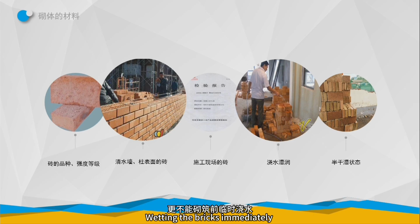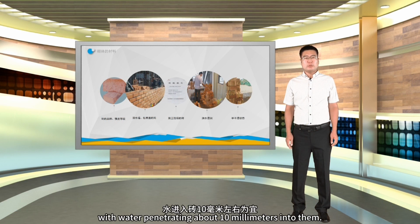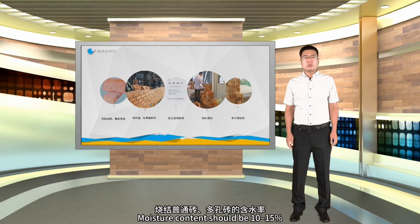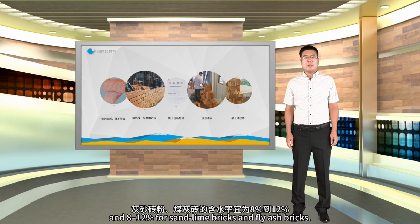Wetting the bricks immediately before masonry must be avoided, as water films on the brick surface will adversely affect the quality of the masonry. Generally, bricks should be semi-dry and semi-wet, with water penetrating about 10 mm into them. Moisture content should be 10 to 15% for fired common bricks and perforated bricks, and 8 to 12% for sand lime bricks and fly ash bricks.